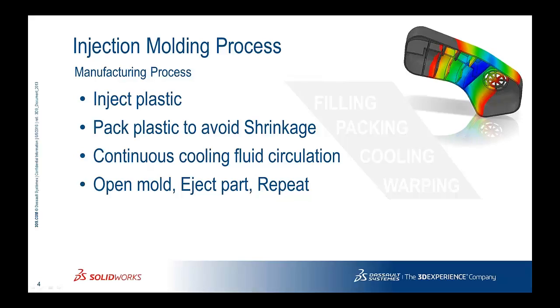And after that, and this is also part of the software, we will see the opening of the mold, the ejection of the part, and also the warpage of the plastic part due to the thermal stress, the difference in temperatures between the plastic part and the outside temperature.